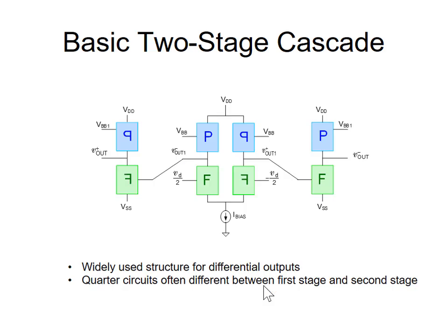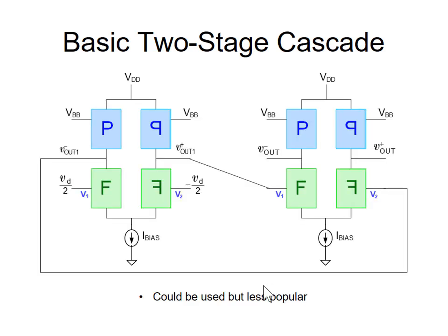I could have differential outputs. And so here I have, on both the left side and the right side, single stage amplifiers with tail voltage bias. Now, when you put a tail voltage bias in, it completely separates the left and the right side, so you can throw away one half of that op amp. And that's why I'm only showing half of it here. This circuit requires a common mode feedback circuit if we want a differential output on the structure.